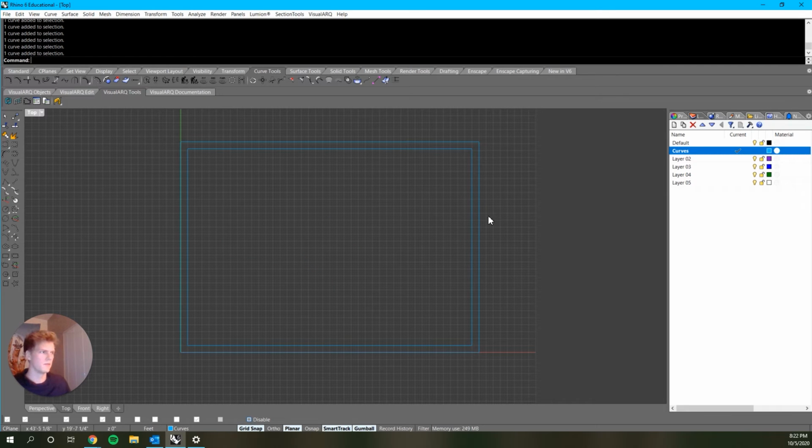You can also then Control Shift click part of that polyline, right? Instead of selecting the whole thing. And we could make a duplicate of that by either running a copy command, copy from here, and then we could snap near and then say just move, I don't know, maybe you want a 10-foot room, right? So you go 10 feet and you see you're bound to sort of that distance.